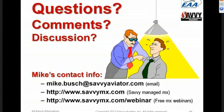And it really is important to make sure that when you take a charging system problem to a mechanic, that you make sure he actually goes through the appropriate troubleshooting steps, as opposed to just assuming that it's the alternator or the regulator that's bad and replacing it on speculation, because frequently it's not any of those. It's a broken wire or a bad connection or something like that. And you can run up a very large bill replacing components that actually weren't the cause of the problem.